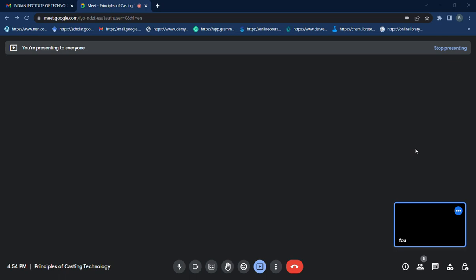So that is the feeding distance, basically the feeding distance for different things. This one is your riser, this one is your riser. We need to calculate at what thickness or at what distance this riser will feed your cast. Firstly, the feeding distance in steel plates is given. These values came after a lot of experimentation, and generally people reported them, so it is an average of a lot of things.